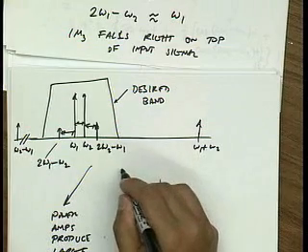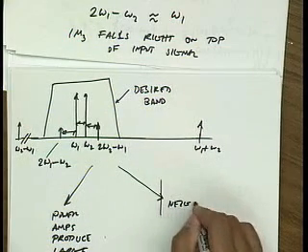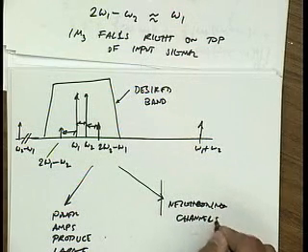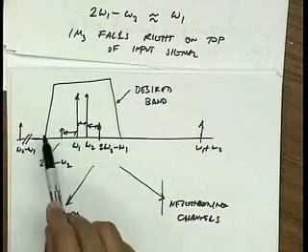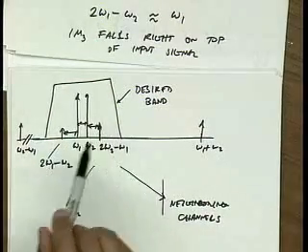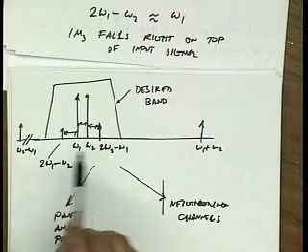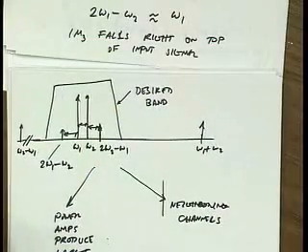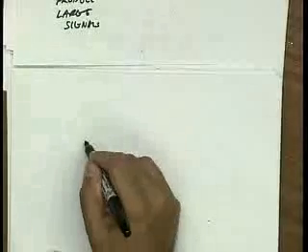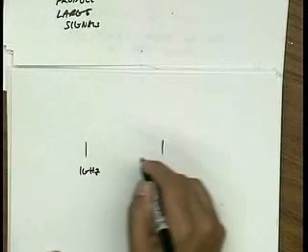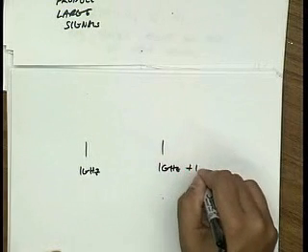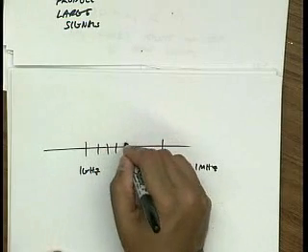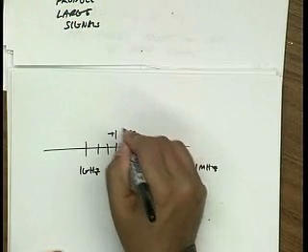And then the other scenario is you still have basically neighboring channels. In most communication systems, even a narrowband communication system, you'd break up your spectrum into multiple channels, right? Let's say you had a megahertz and you broke it up into 10 100 kilohertz channels. Okay, so let's do a very simple example. Let's say this is 1 gigahertz and this is 1 gigahertz plus 1 megahertz. So an extremely narrow band system, and I divide this into, let's say, 10 channels, each 100 kilohertz.